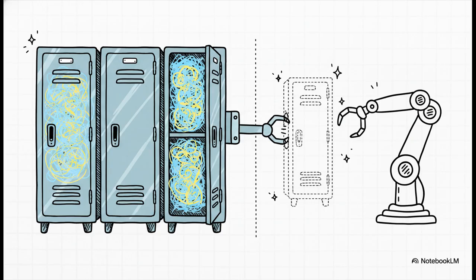The hardware dynamically allocates brand new, hidden registers completely on the fly. Think of it like duplicating resources to avoid fights, giving workers their own temporary lockers so they don't bicker over the same one. If two out-of-order instructions both want to use register 3, the processor secretly just hands one of them a completely different hardware locker behind the scenes. This brilliantly eliminates the storage conflict without the original program ever even realizing it happened.